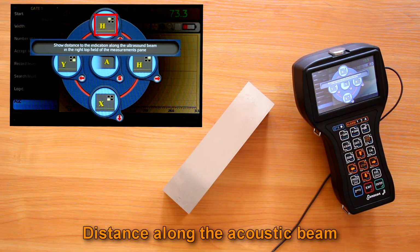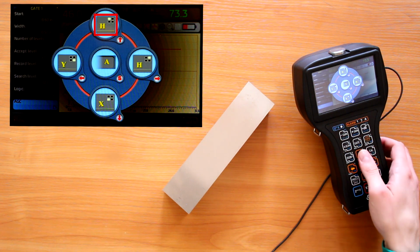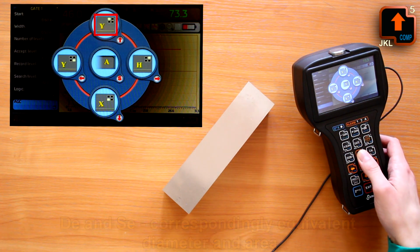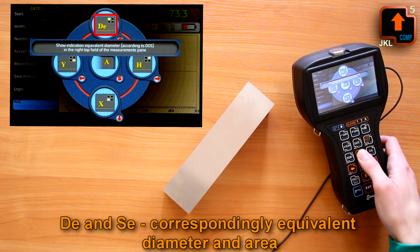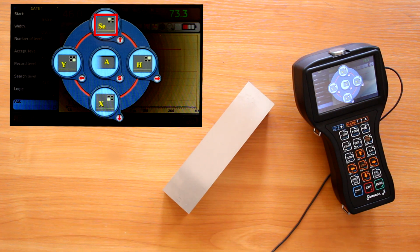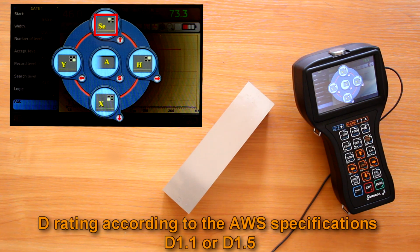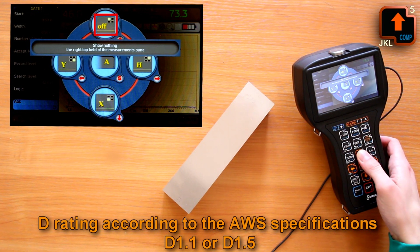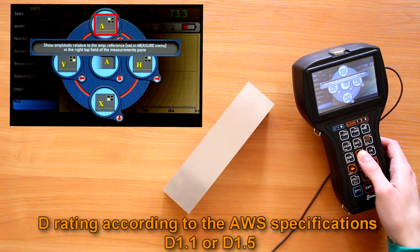distance along the acoustic beam, X and Y coordinates, equivalent diameter and area available if DGS system is on, and D rating according to the AWS specifications D1.1 or D1.5 if it's on.